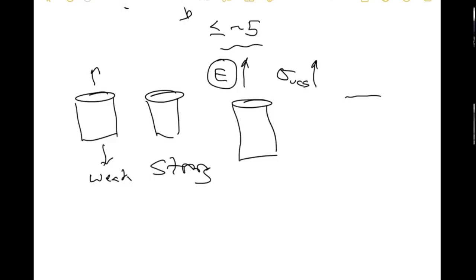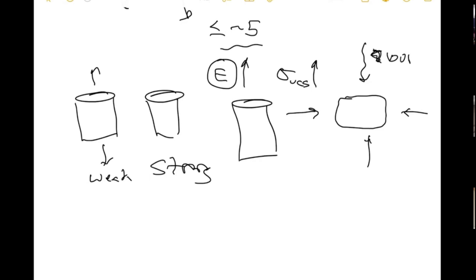This is an excavation, deep underground. And there's high load coming in both ways, typically underground. Underground, the load is pretty much always compressive. So this might be really, really high, like 100 MPa. This might be 20 MPa. Like in a gold mine, it's even higher than 100 MPa.